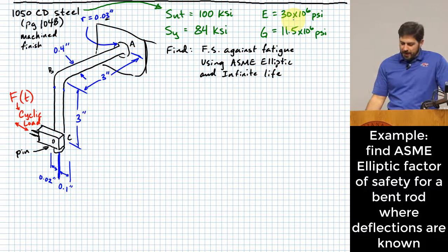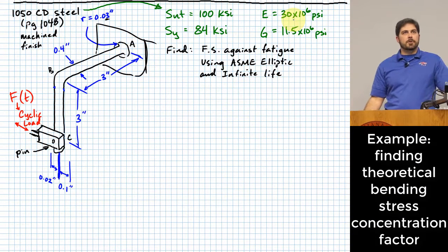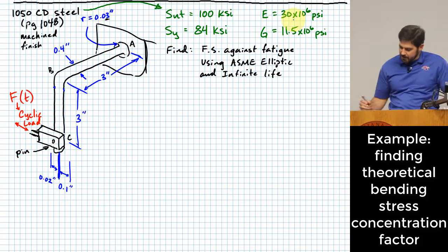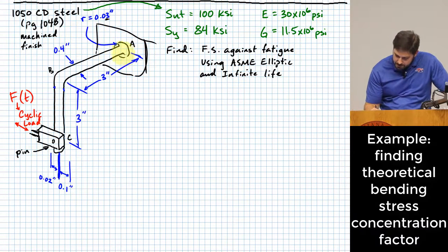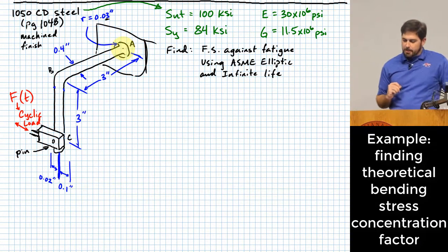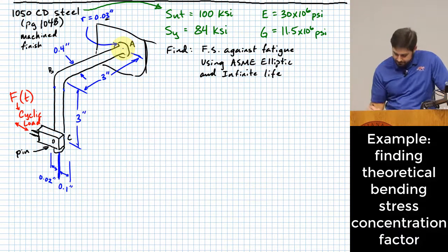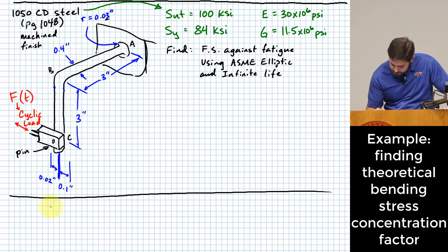Here's where I frequently start. I frequently start by finding our stress concentration values. Okay, those usually don't depend on a whole lot, right? You don't have to find other things first, and usually a whole lot depends on them. And so I'm going to go ahead and start with that part of the problem to get that part knocked out. So, we are going to have stress concentration factors that apply where this rod goes into the wall right here. Okay? So stress concentration.